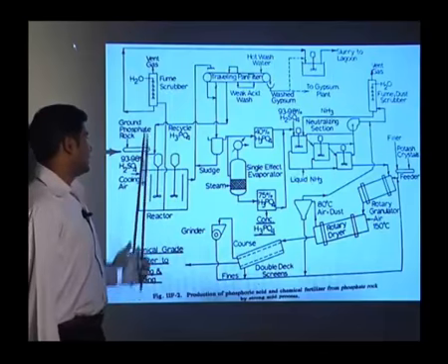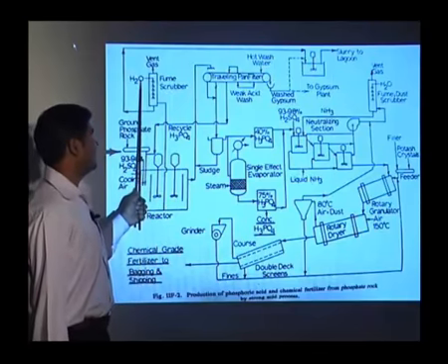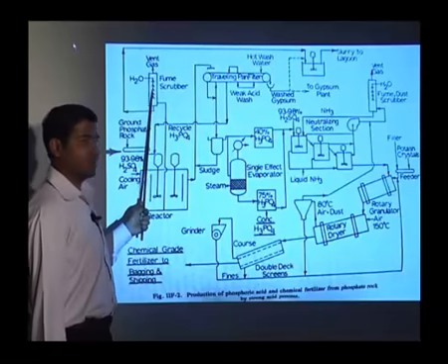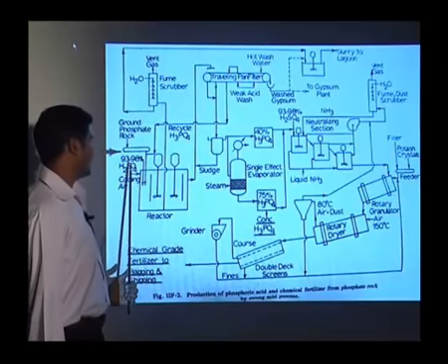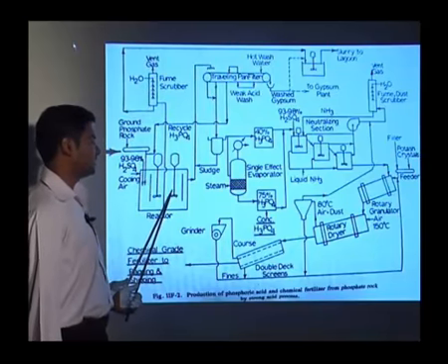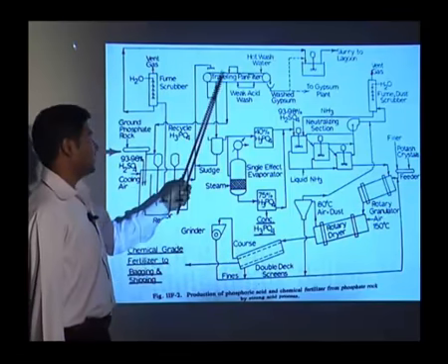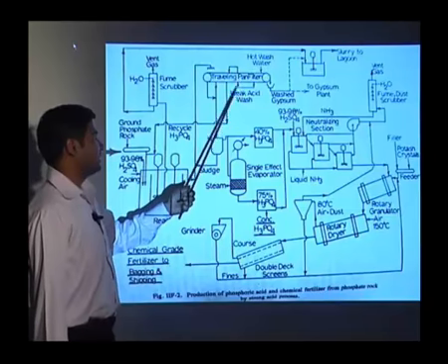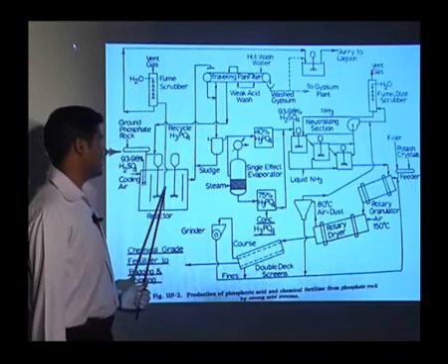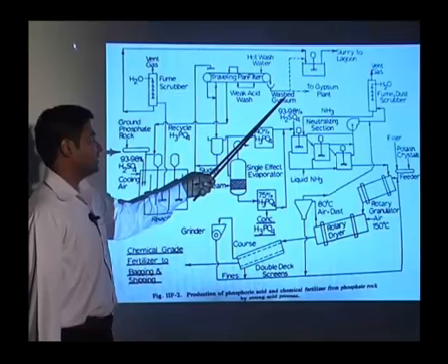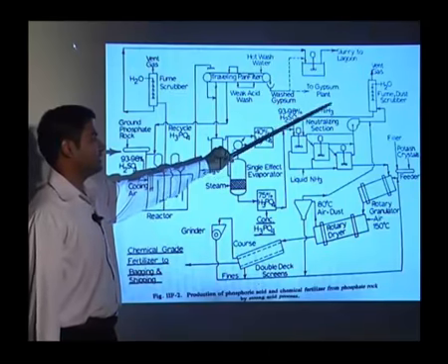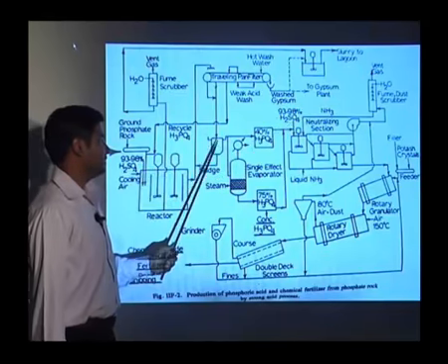So if you see, whatever the waste gases, they are recycled over here. So phosphate rock and the sulfuric acid will give you the gypsum and the phosphoric acid. Then we are washing it. Whatever the weak acid wash, we are recycling back. Then gypsum we are washing, and then we are sending to the cement plant. Then we are getting the phosphoric acid.